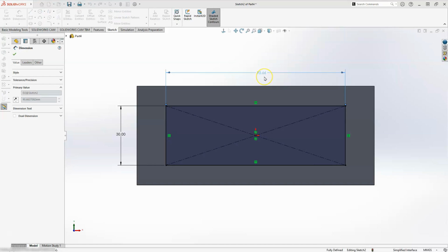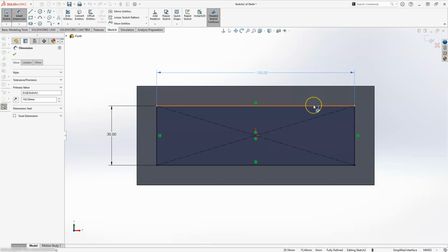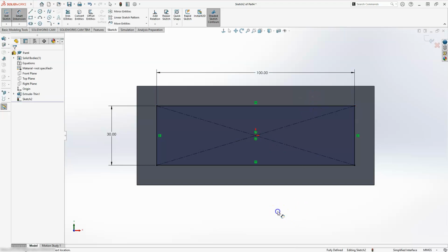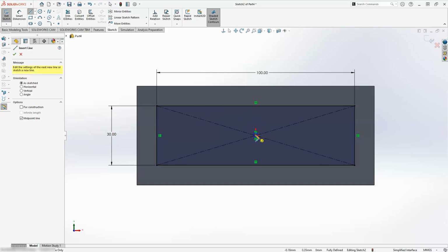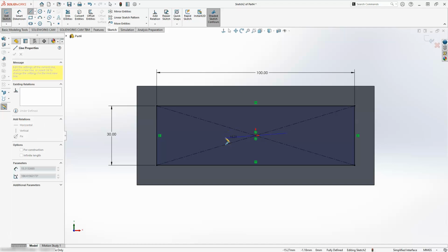All right, now we have this outside rectangular kind of part created, right? All right, so for the next part here on the inside, I'm just going to do that midpoint line again. So let's go to midpoint line. I'm going to select this midpoint, and then I'm going to come out this direction. And now I have to do a little bit of math again, right? So I have a number of 86, which is how long or how far it is from one edge. And then I'm going to subtract the other distance, which is 34, from the other edge. And that's going to give me the length of that line, which should be sitting at 52, right? So all I did is took the 86 minus the 34, and that gave me a length of 52.